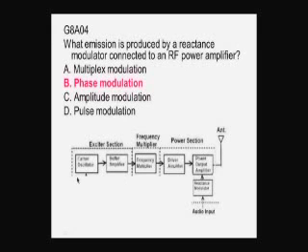And to do a true frequency modulation, we would have to be applying that reactance modulator back here in the oscillator. And you can see that I actually did some cutting and pasting here because you can see just the tip of the arrow where I stole that reactance modulator to move it over here to fit the question. Okay? What you'll get when you apply it to a power amplifier is phase modulation that we saw in the diagrams earlier, because we can't change the frequency at this point. We can only change the phase when it's applied to an RF power amplifier.